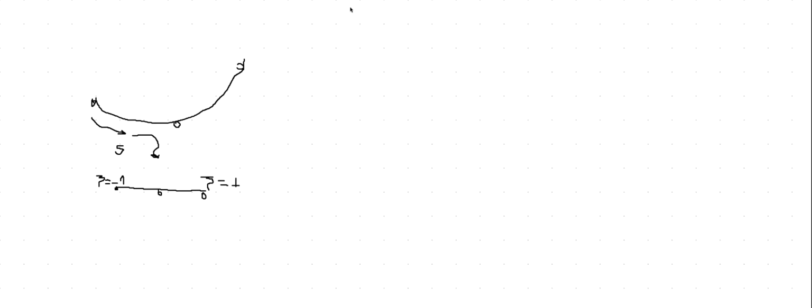First of all, if you have your interpolations, oops, so this is your true element. It might have 3 nodes. Let's say node 1, node 2, and 3. And you have measuring this the coordinate s. And then you're mapping every point into the, let's say, isoparametric element, which has these nodes 1, 2, and 3, that are sitting from psi equal to -1 to psi equal to +1. So this is your transformation s of psi.